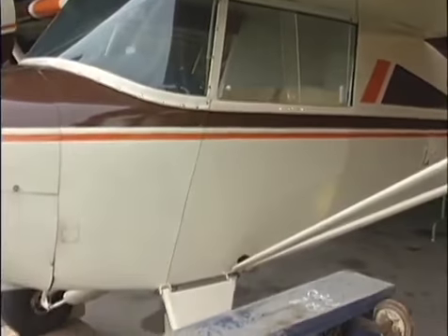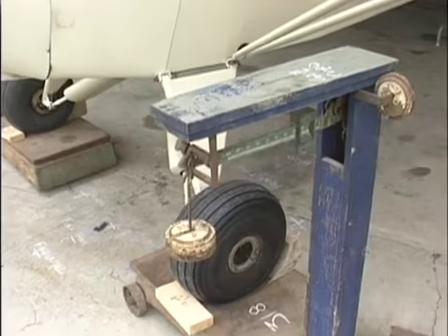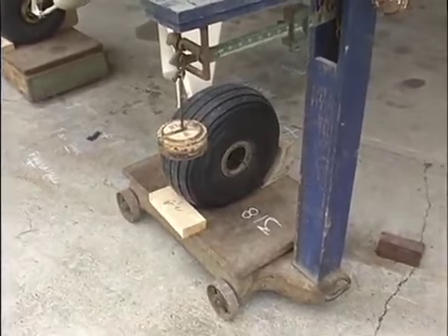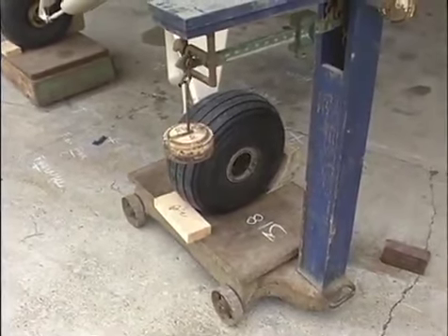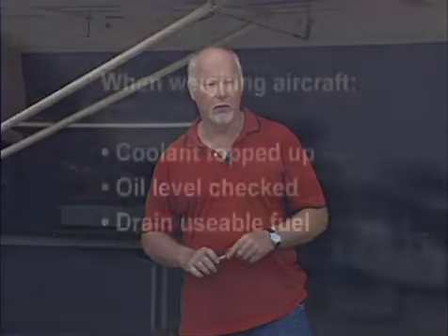When you weigh an aircraft, you've got it sitting on scales, and you don't have the brakes on. You can put a force onto the scale, just like putting brakes on a car. You have a torque that's put on the wheel, on the axle, and it could be acting on the scale, and it's going to throw your weight off. So that's why you want to have it chocked up so it doesn't roll around on you, but you don't want to have any brakes set.